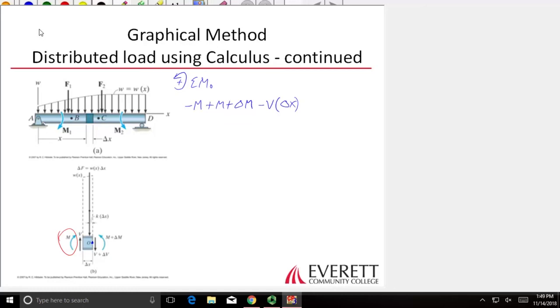Okay, one more force that would create a moment, and that's that top force, the point load. The magnitude of that point load is wx times delta x, and it's going to be a positive moment. The distance from O is that constant k multiplied by delta x. So that comes from right here. Basically what it's saying is we don't know the shape of the distributed load. So when we put a point load there, it's not going to act right in the center. It's going to act some distance from the side. K would be a third if it was a triangle. But we don't know what its shape is, so it's just a constant.